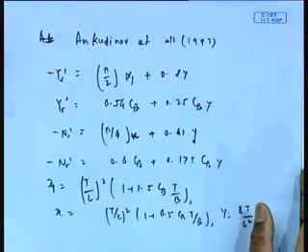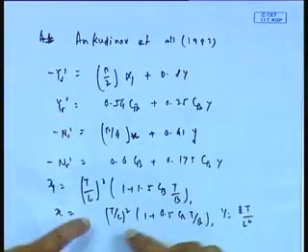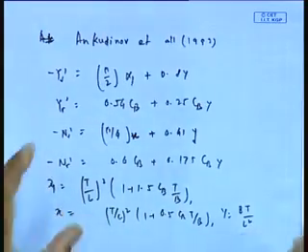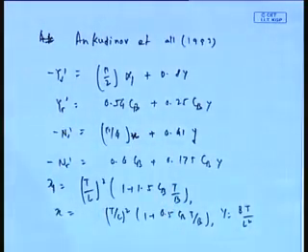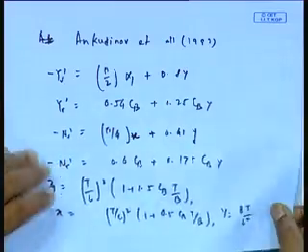Most of the companies who are doing it have proprietary data. So you don't know what formula they are probably using. But there is another set of formula. There are more sets there. The important point is that even here T by L square is the important parameter. It is T by L square into some corrections based on B by T, B by L, CB, etc. Okay. So there is no end of it.